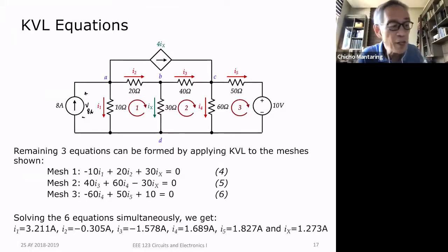No? Basta ang definition ng essential branch is an essential branch is a path that connects two essential nodes. Right? So this is an essential branch because it connects A and C, no? And both A and C are essential nodes. Okay. If I had put a resistor here, this whole thing is still an essential branch. Because this is only one path that is connecting this essential node and this essential node, no? Remember the definition of an essential branch is it connects two essential nodes without passing through any essential node.